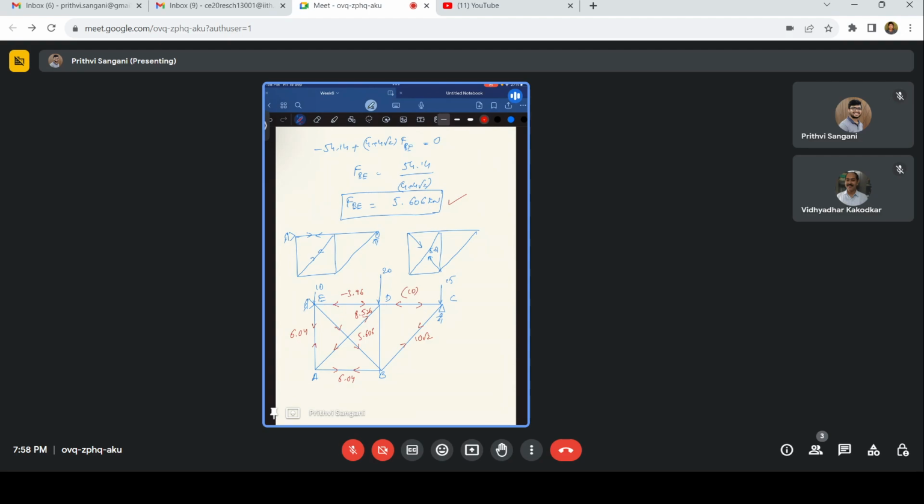Delta H is going to be, Fi Li by AE is already given, that is alpha delta T. This is my displacement. PL by AE is nothing but the delta, right? So instead of PL by AE, here we have thermal expansion. Due to thermal expansion, the displacement is alpha delta T into L, sorry, alpha delta T times Li times Ui, which is square root of 2.